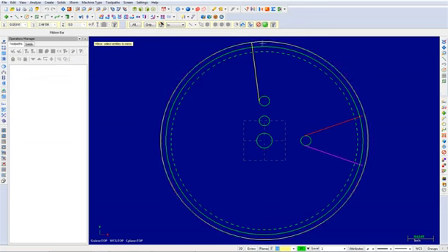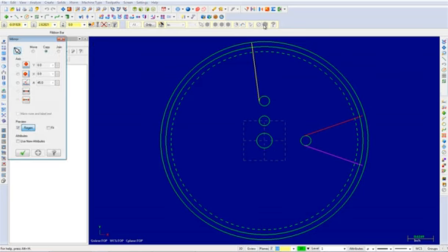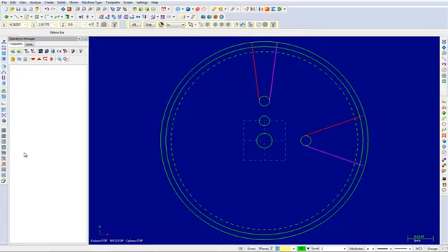Again, choose the End Selection button. The Mirror dialog box will appear once again. Again, ensure that copy is enabled. This time, however, pick the option to mirror about the Y-axis. Once complete, choose the OK button to exit the command. Now, in order to return the geometry to its original colors, choose the Clear Colors icon. Your part will appear as shown up to this point.